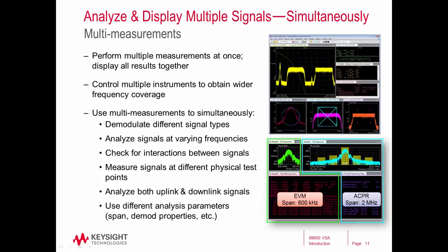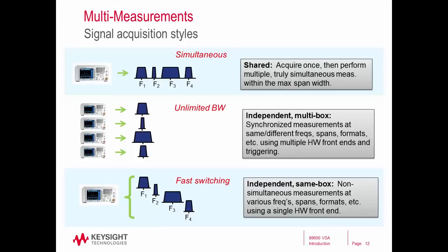Also, you can vary the parameters of your analysis between the measurements that you have configured. So you can set different spans, different demodulation types, different frequency. All of those parameters can be set independently. This slide summarizes the different modes that can be used for multi-measurements.